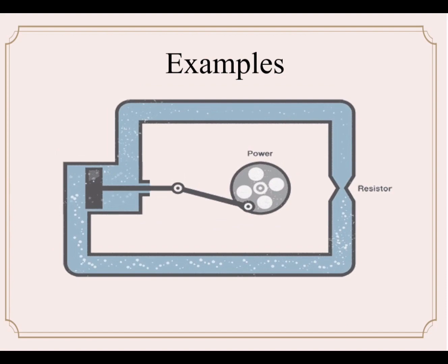Alternator. AC can be produced by using a device called an alternator. This device is a special type of electrical generator designed to produce alternating current. A loop of wire is located inside a magnetic field, which induces a current along the wire. The rotation of the wire comes from different sources like a steam turbine, a wind turbine, flowing water, and so on. Because the wire turns and enters a different magnetic polarity periodically, the voltage and current alternate on the wire.